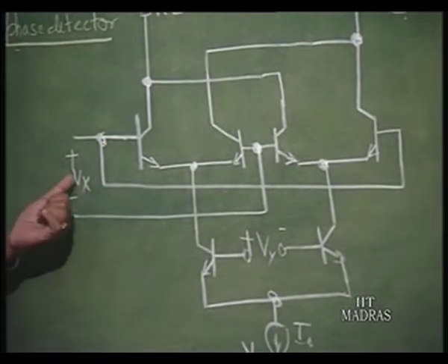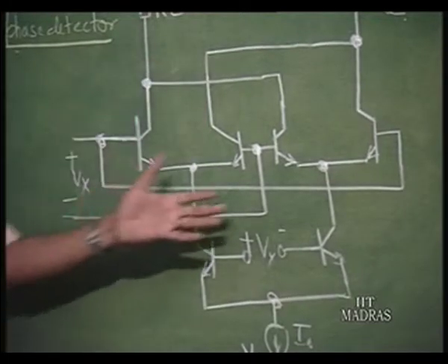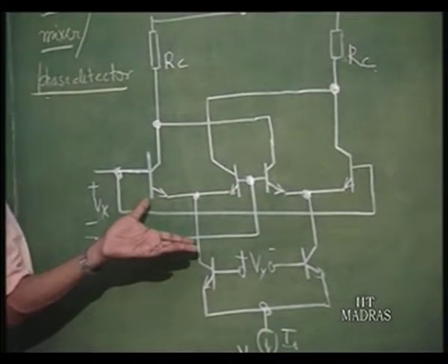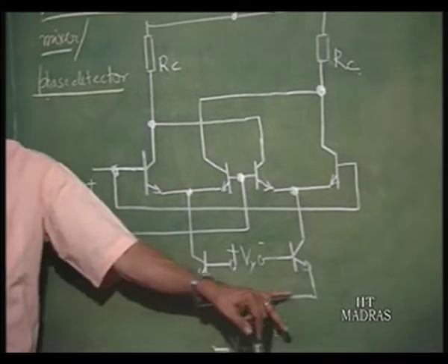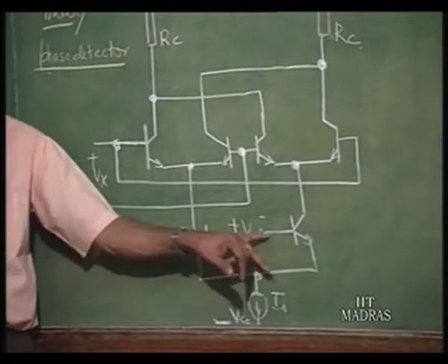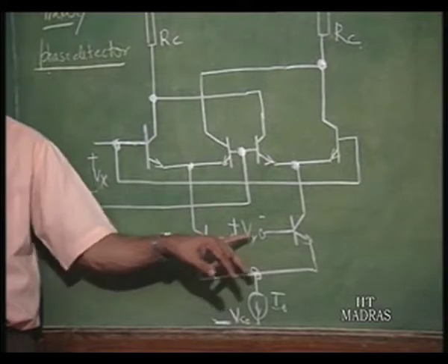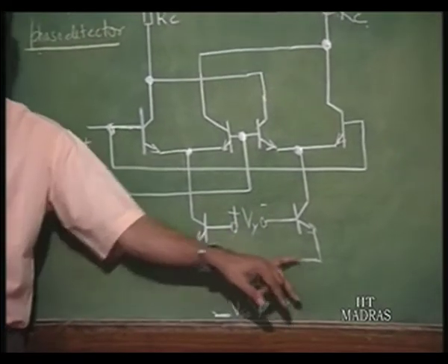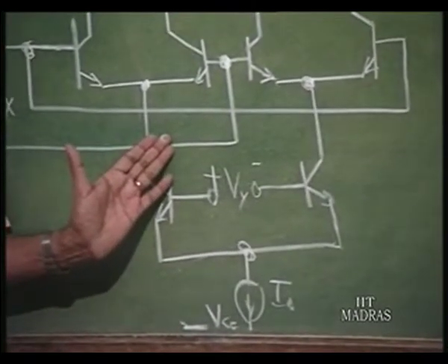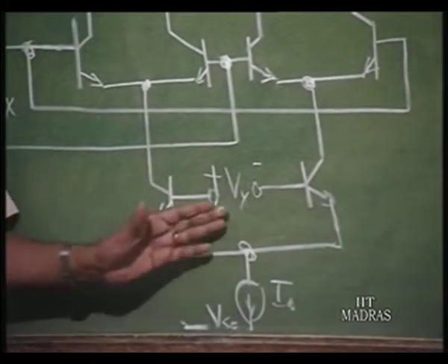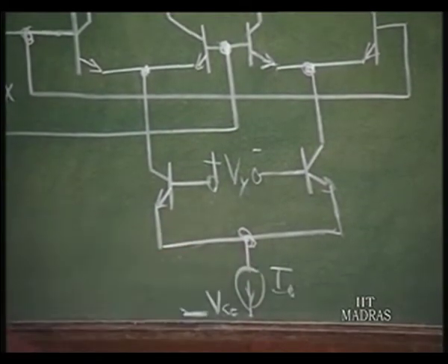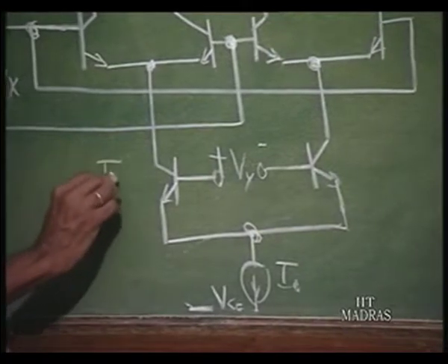So, directly the signal can be fed to this block, which we had seen as the output block of the precision multiplier. Here again we can get rid of that R y resistance and make use of the fact that when we apply V y here, this V y divided by twice R e of the transistor itself will convert it into a current. So, this particular structure is going to have I naught here, and current here is going to be I naught